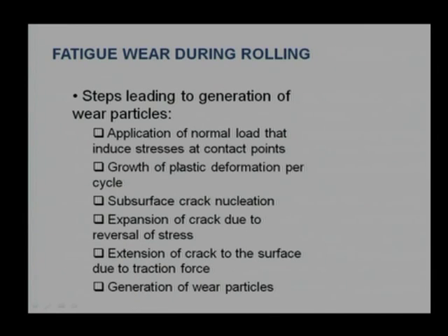Now, we apply a normal load, not a very high one, but one which induces high contact stresses, and there is a possibility of elastic and plastic deformation. Elastic deformation is not a problem for us, it will regain the shape, but there is a possibility of plastic deformation, some sort of depth in that.